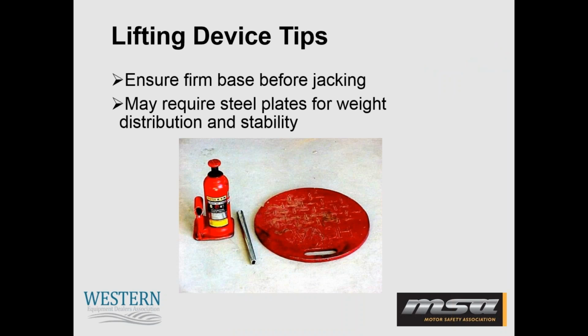Now that we've taken care of those items, we want to ensure that we have a very firm base before jacking. And always place the jack on that hard level surface capable of supporting the weight of the load. This may require steel plates for weight distribution. And utilizing a flat plate under the jack will ensure that stability, such as seen on this picture.